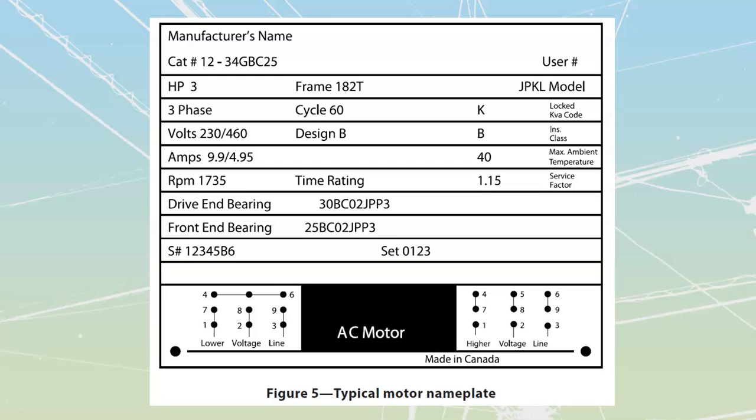Let's talk about nameplate information now. First of all, let's talk about the one extremely important thing that is missing off of this nameplate over here. If you want a challenge, pause the video for about 30 seconds. Take a look around, see if you see the one thing that is highly critical that is missing. For those of you that aren't up for a challenge or just bored, what you should note is that there is no certification mark on here.